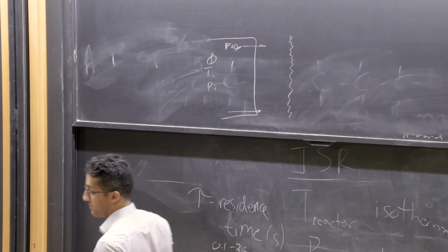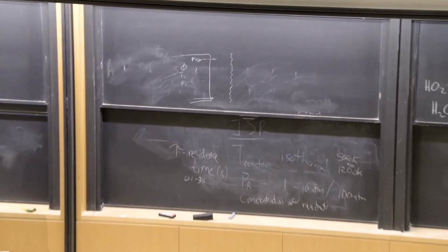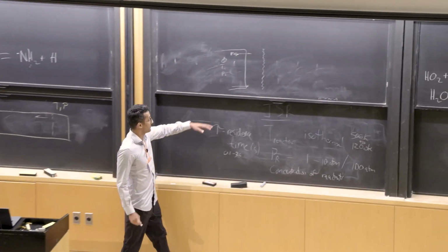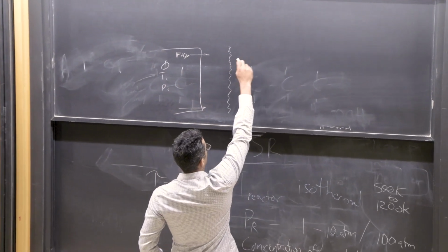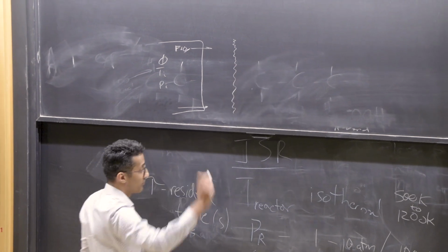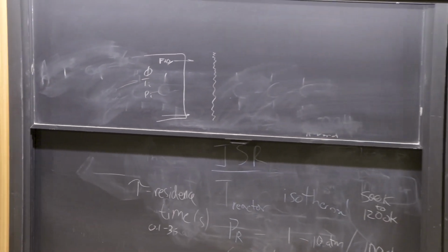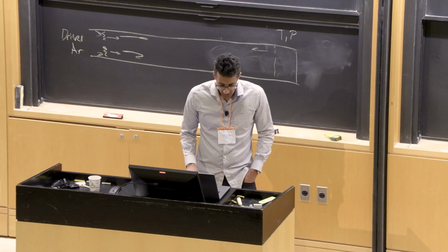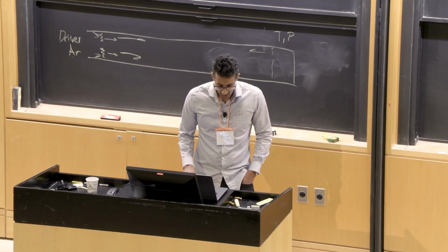And of course, because you have a flame, you have exothermicity from the flame, so you have temperature gradients along this direction. The temperature should be rising as you go into the flame. Species like the fuel and the oxidizer will be consumed, intermediates will be formed, and there are a lot of interesting things that can be observed. You have a preheat zone, where the fuel starts breaking down.